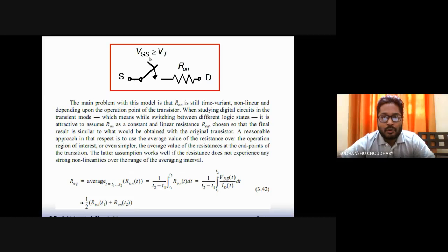Okay. So a MOSFET is used as a switch. Now, obviously, this switch has some resistance because unless you have a channel, the resistance is very high. When you have a channel, again you have some on resistance because of that channel. The channel also has some resistance, so there is some on resistance. This on resistance, that is the channel resistance, varies with the applied gate bias. That means it's a non-linear quantity. So one has to linearize it, that is, make the value of this resistance constant for manual analysis or even circuit analysis.